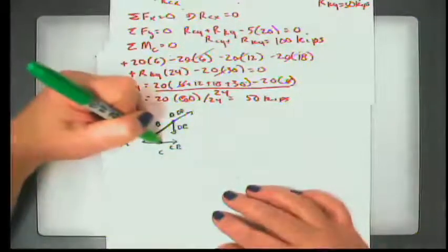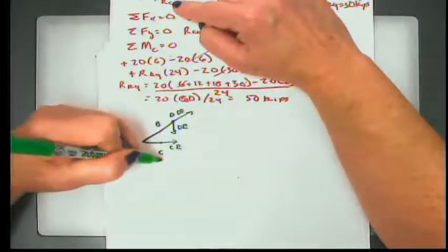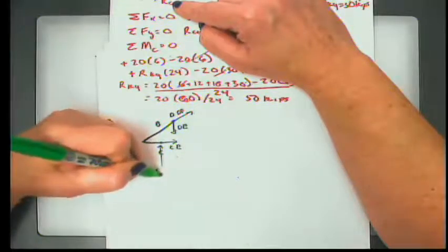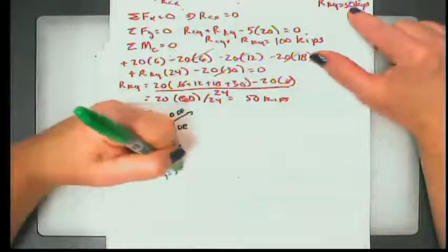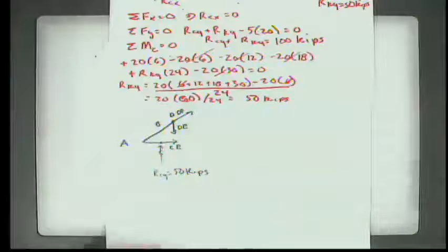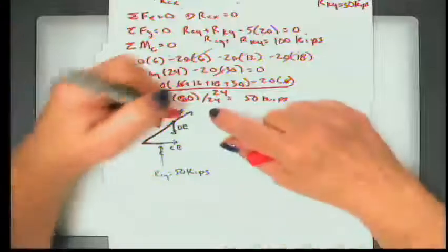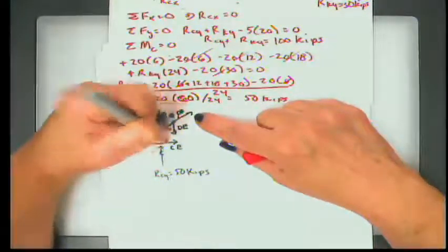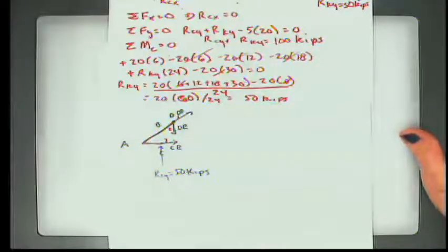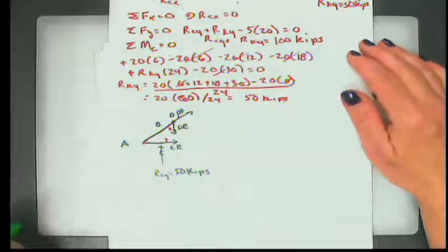and away we go. So what else do we have going on this truss? Well, we have a reaction at C in the y direction, which is pushing up. And I know that value is 50 kips. All right, so that means, kind of wish I'd drawn this truss like this. Okay, so I have one force, two forces, three forces, and I can solve directly. Everything that is to the right of my cut, I can ignore, because this section of the truss also has to be in static equilibrium.